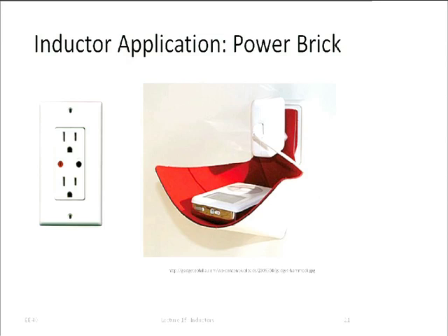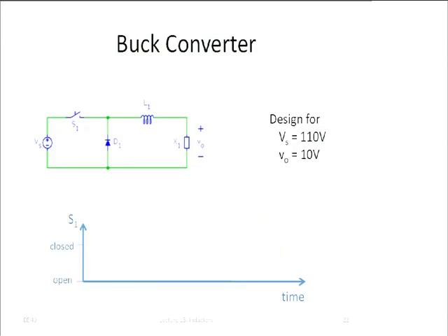I don't want to go through the circuit completely again, but what we really are doing is setting up a current in the inductor by closing that switch, so power gets transferred from the source into the inductor. Afterwards, when we open the switch, the current keeps flowing now through the diode D1 and through the load because the inductor has stored energy, right?